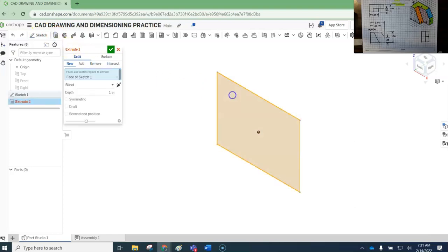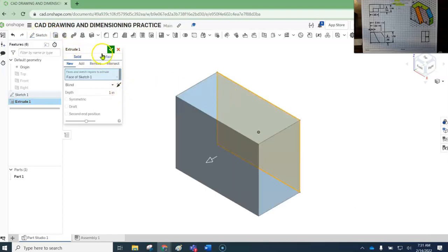So we'll click extrusion. Click the area that we want to extrude. I'm going to call this main. Just when I hit my caps lock on, I call that main, just so that I know that's my main block, because that's the overall original block that we're going to work from. The thickness we're going to extrude is visible up here in my case, in the top view. You see the overall depth is 0.5 inches. So we'll highlight the 1 inch and type in 0.5.